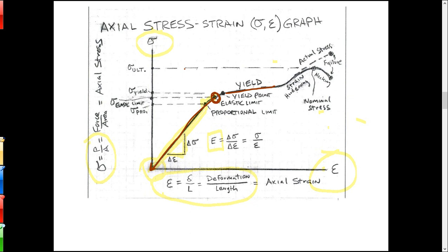Okay, so there's an initial kind of rise in the graph, then a flat yield. The second time, all these fracture lines are kind of interfering with each other now, and that material can't stretch out so easy anymore. So that's the second hardening phase. And eventually then it will fail, okay? It'll break. So that's kind of a classic graph for a material.